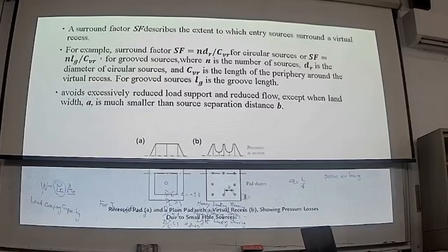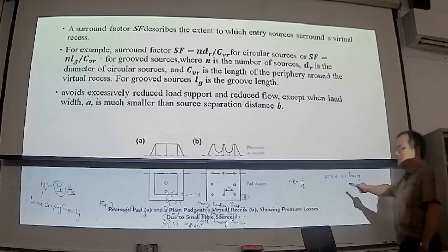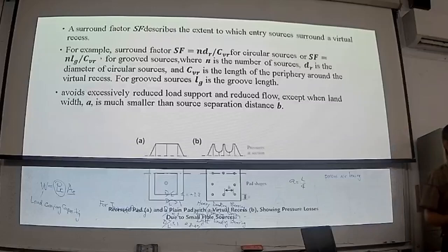But the difficulty is how you can manufacture the porous material homogeneously cover whole bearing area with equal porosity of the material. That is a very tricky one.